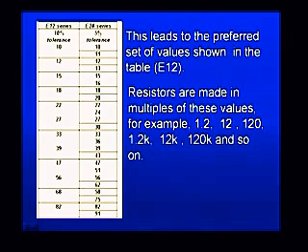If I go to 5% tolerance, obviously you can see the overlapping will be limited, and therefore we have to introduce more values in between, so that the intermediate values can be obtained from any set of these values of resistors. So the 5% tolerance will be manufactured for more preferred values, as you can see in this table.